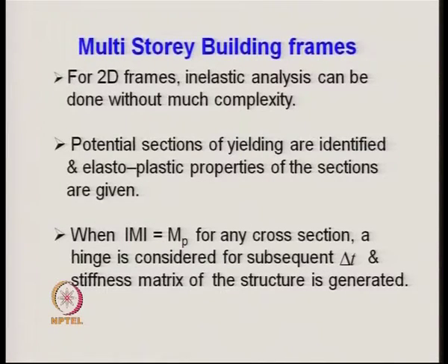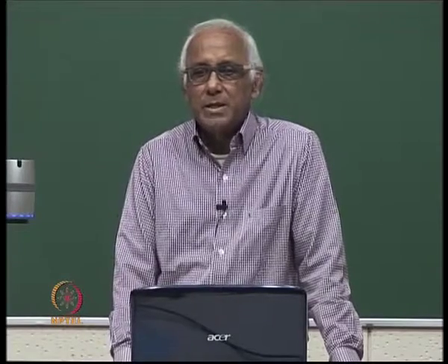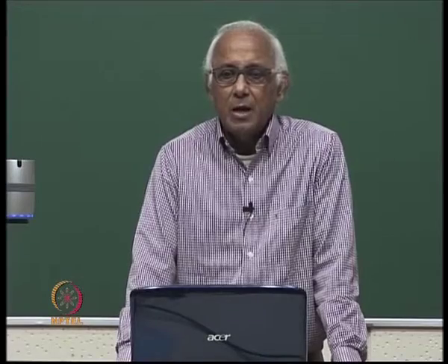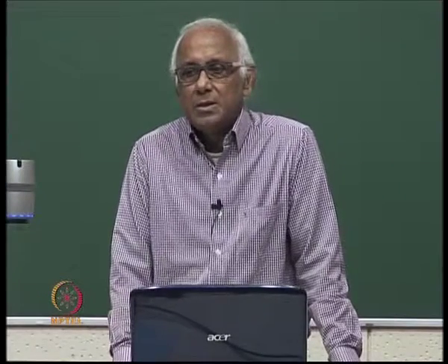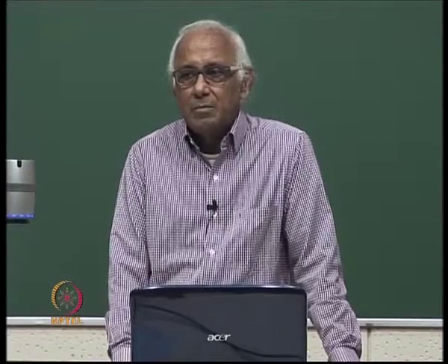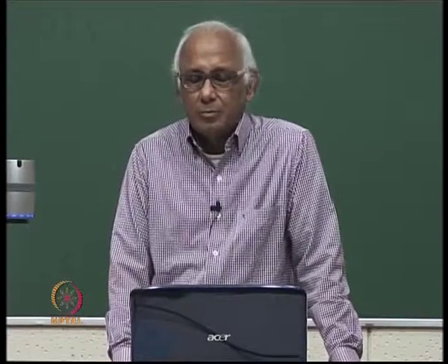At those cross sections we check the bending moment, and when the bending moment at that cross section becomes equal to the plastic moment, or the moment carrying capacity of that cross section, we say that that particular cross section has yielded. For the subsequent delta t or subsequent increment of loading, we consider an ordinary hinge to be present at that particular cross section, and accordingly write down the stiffness matrix for that particular element or column.